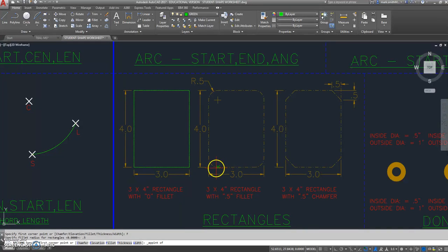Now with apparent intersection I can get two things. I can get my intersection that I have normally, and I get my rectangle, my square for apparent intersection. We want the square to be showing, not the intersection. So I click that, and then when I hover over the other one, you see the intersection appear where the circle or this corner would be if there was a corner. Notice how the fillet automatically begins to be created.